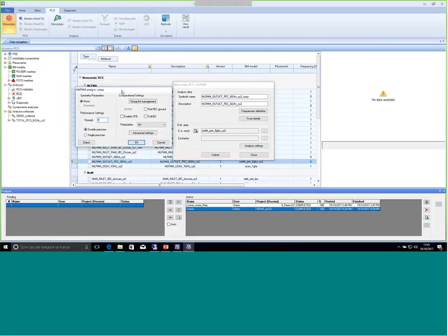In Galileo EME, for the MoM-based solvers, we have the electric field integral equation and the combined field integral equation as well. We have the capability of treating dielectric materials with a surface impedance approach, exploiting the impedance boundary condition approach, or we also have the Poggio-Miller-Chang-Harrington-Wu formulation that allows us to model a real high-fidelity three-dimensional model.